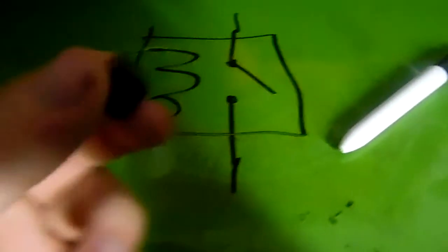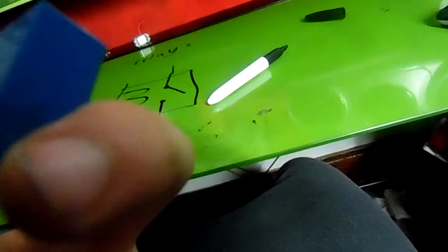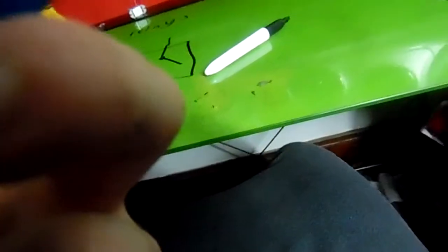That's a 5-volt relay. Here's another 5-volt relay. Here's a 12-volt. Let's see if you guys can see this or not. Basically it says 5A at 240 volts AC with 5 amps at 30 volts DC. And this is a 12-volt coil voltage. This is the same thing.